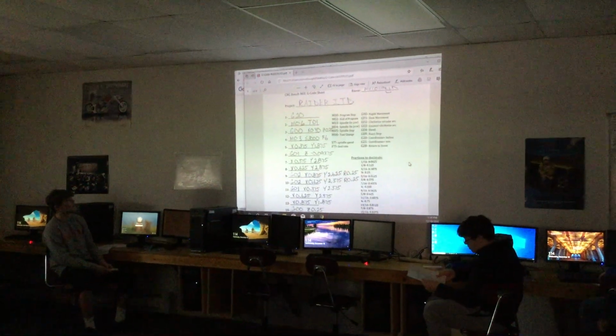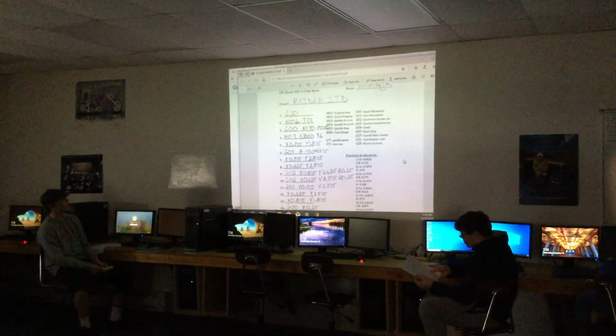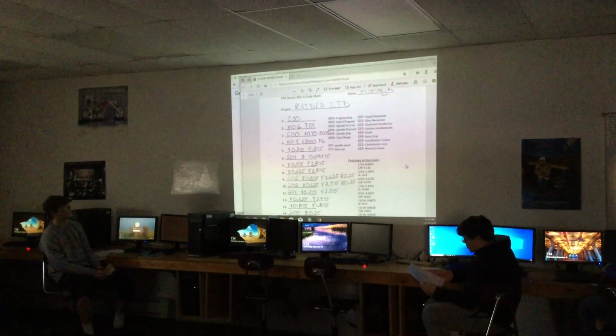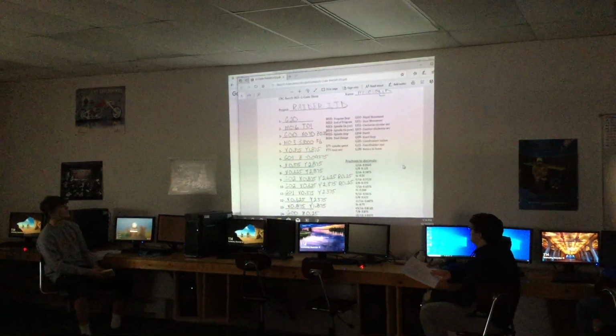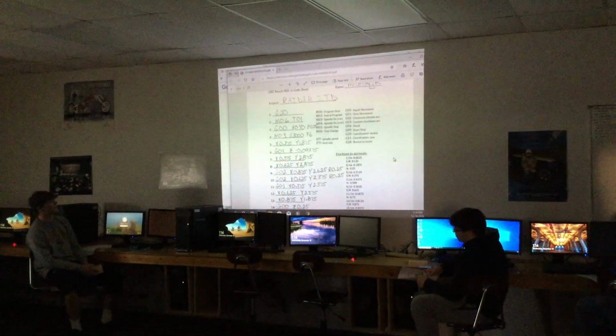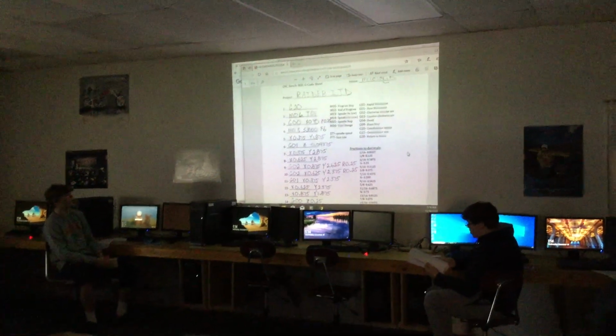Spindle speed. You can change that spindle speed, just like the router in the wood shop: the bigger the router bit, the slower the RPMs you want to use. The smaller the bit, the higher the RPMs. I think this goes up to 5,000 RPMs. I haven't turned it on that far. But when you change bits or use the edge finder to set your X and Y coordinates, you actually have to slow it down to 500. You don't want to spin at 3,000 RPM when you're trying to set that. So there are different things you have to use for this machine.